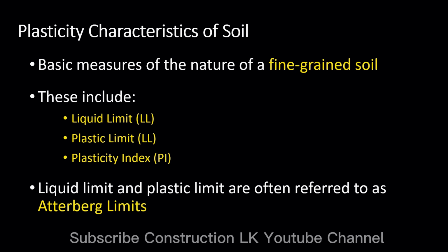Liquid limit and plastic limit are often referred to as Atterberg limits, in recognition of their formulation by the Swedish soil scientist Albert Moritz Atterberg. In this video we cover the test procedure of liquid limit determination by Casagrande apparatus and penetration method, and also the test procedure for the plastic limit determination.